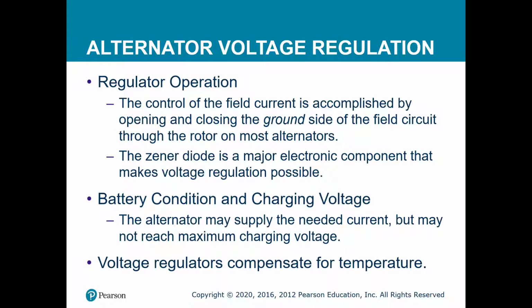In a moment, I'm going to play a video from Films on Demand that will show the 3 different types of voltage regulation that are out there: mechanical, remote solid state, and then internal. Well, they left out a 4th one, probably because the video is slightly dated, but nowadays it's remote again, being done through either the body control module or some type of charging module that's responsible for charging system voltage. In some cases, and we'll talk some more about computer-controlled charging systems, based on the battery's condition, it can actually affect the charging system voltage and amperage rates.